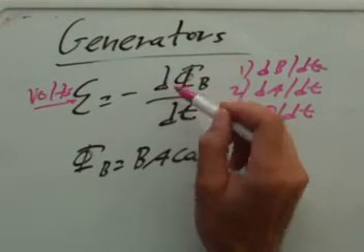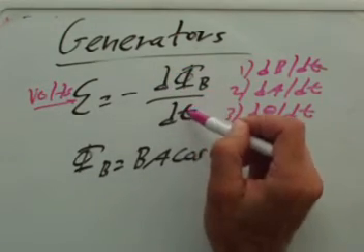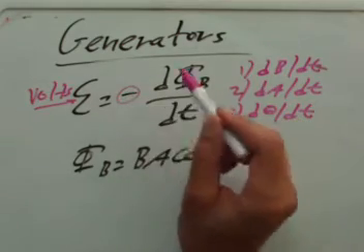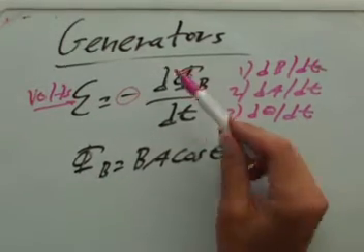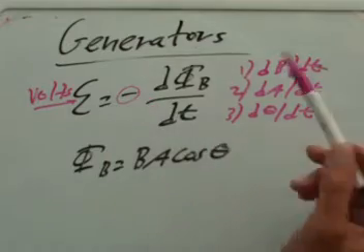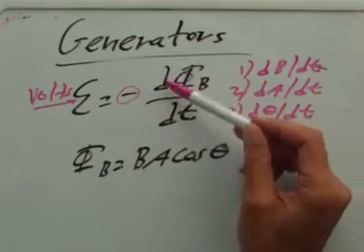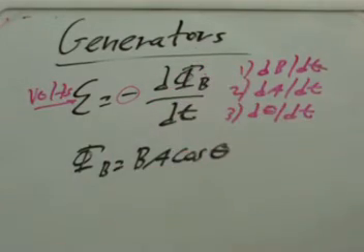So the time derivative here is directly mapped to the word change in Lenz's law, and the minus sign is directly mapped to opposes in there. So you have it all together. It's changing magnetic flux, and there's the opposed. But the point is that if you can have a non-zero time derivative of your magnetic flux, you'll get volts out. That's exactly what generators do. They produce volts for us so we can run our houses and our electrical devices.